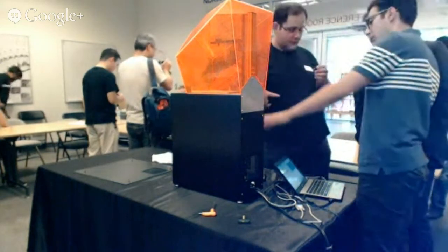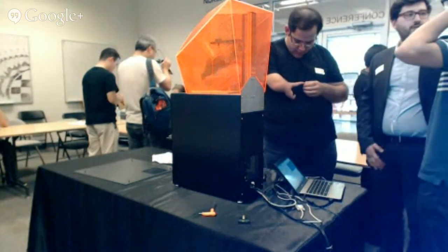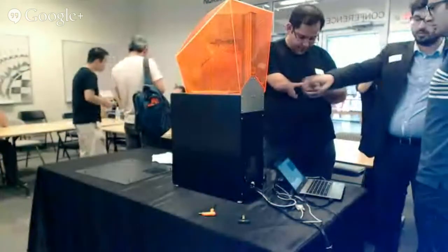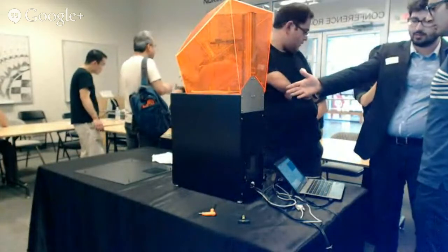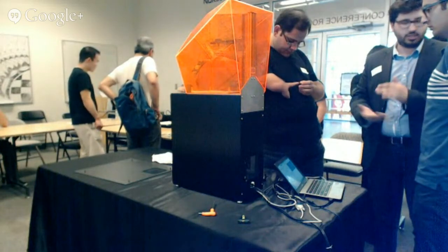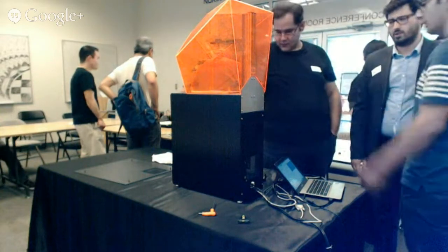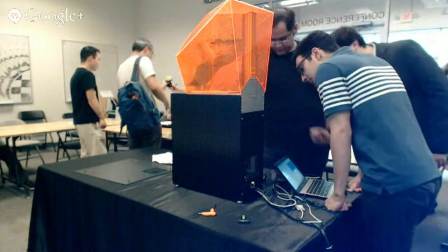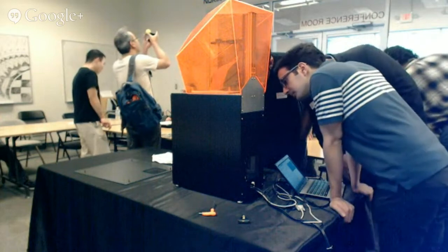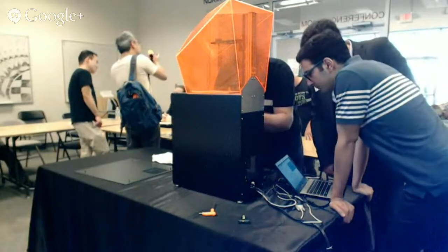In this case, I printed also with harder layers, right? 1470 exposure, more than twice as much exposure each time. So the whole thing came out harder, and also it shrank as it was being printed. And so that means that the overall shape resists warping. And warping at a macro level has a lot to do with the way that the part is designed. Because if you have a thick part and a thin part join each other, they will warp volumetrically differently, and that'll cause all kinds of strange effects. So there are various design principles when you're designing something for injection molding to try to reduce those effects.